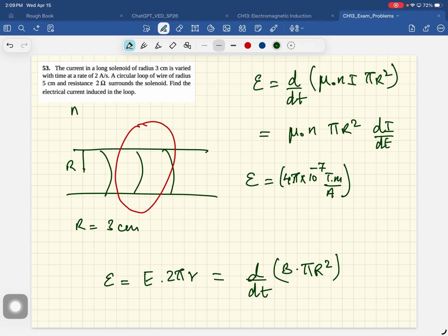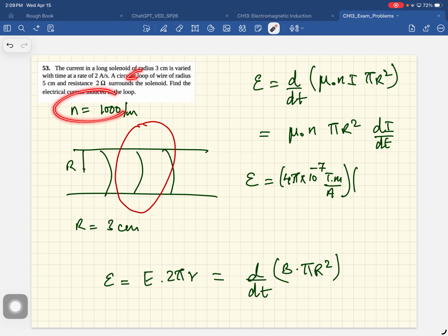This problem says a flat square coil of 20 turns that has a side of length 15 centimeters is rotating in a magnetic field of strength 0.05 Tesla. If the maximum EMF produced in the coil is 30 millivolts, what is the angular velocity of the coil?